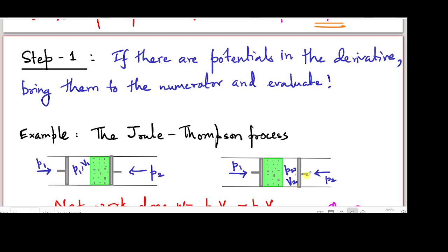Of course, it's now at a different pressure, so it would typically have a different volume as well. Whether it will be a lower volume or a larger volume will depend on both the equation of state, the temperature which it reaches at that point, as well as typically the pressure head that you have, the difference in pressures. Now, this whole thing is supposed to be enclosed in an adiabatic environment. No heat can flow. Now look at what the net work done on the gas is.